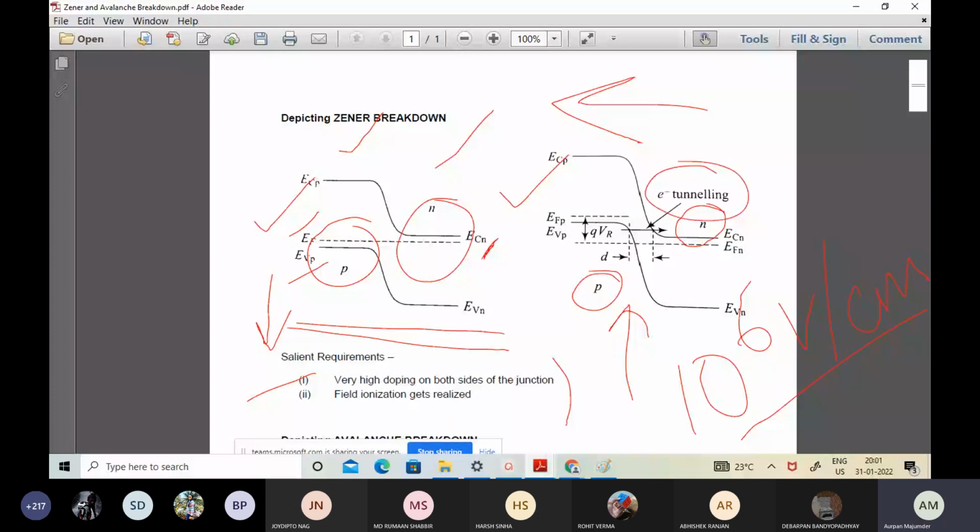One thing I would like to mention, that under reverse biasing, two kinds of transport phenomenon can happen. One is that you have to surpass the hill or the potential barrier, through which very less amount of electrons participate, as we all know, under lower potentials. That is the one which we know under the case of classical mechanics. And the other one is the idea of quantum mechanics, where we have to think of the particle through the idea of a wave function of a particle. Hence, we need to understand the particle's movement utilizing the Schrodinger wave function.